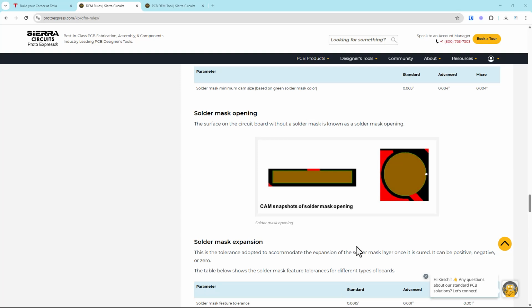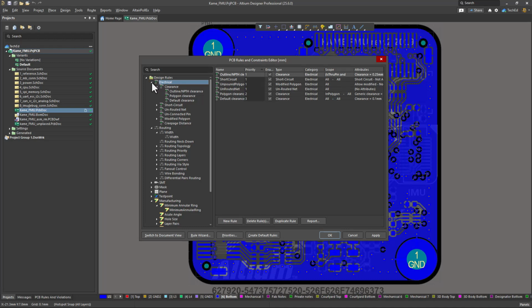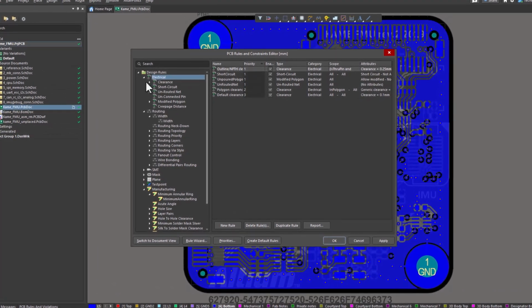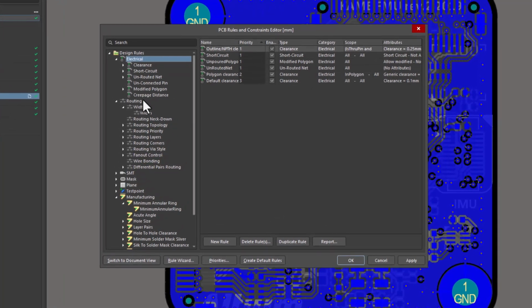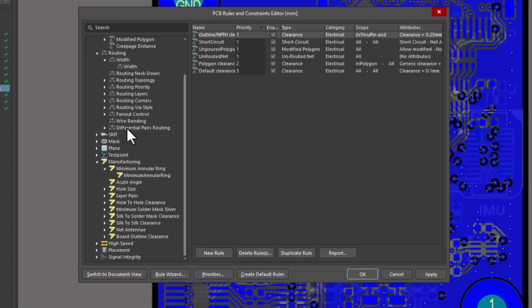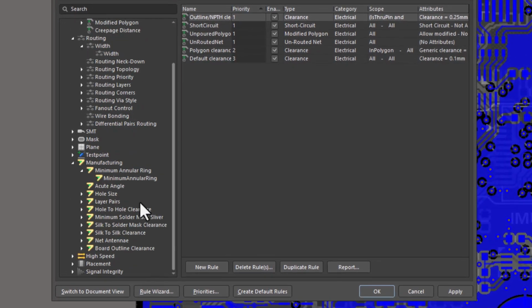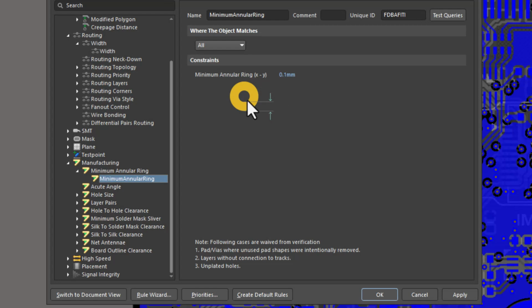In Altium Designer, where would you set that? Typically, you're going to find things like design rules, electrical clearance, and so on. To get here, you would go to your PCB, so part of your project, and design rules, okay? People are used to setting your electrical with trace width, your routing, all that stuff. But what you need to do is go down to the manufacturing rules. I never see this, okay? Well, not never, but I don't see this often enough in a lot of guides.